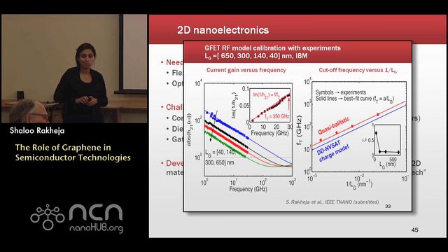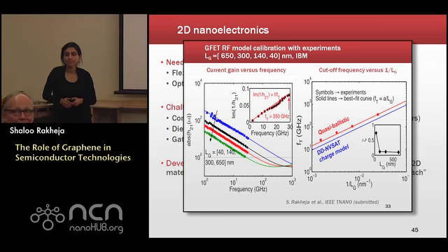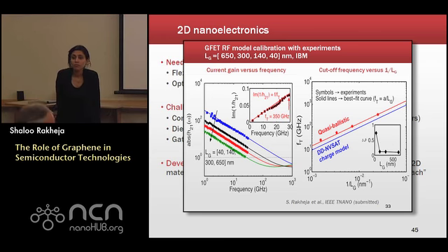And other questions? So you showed the IV curve in the graphene FET, and it was asymmetric in the electron branch and hole branch. And you said that it is because of the different coupling to electrons and holes. But when the band structure is symmetric, the electron and hole have the same effective mass, and you cannot say actually whether it is electron or hole.